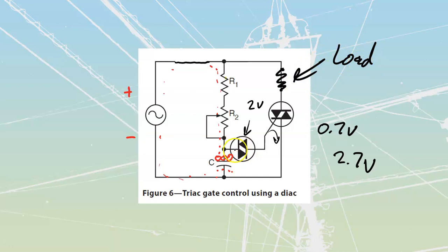All right. Over here, we see that these two are going to be in line, and they act as if they are two switches. Once we reach the proper value of voltage for both of these, both switches are going to close. This 0.7 is going to be met. This 2 is going to be met. And we are now going to run current through there. What current is going to run through there? Well, if I take a look at it, I'm going to run off this current through there. Those electrons are going to leave from here because they can travel through here. They're going to travel through here, back through this. Remember, it can take current through in either direction to drop the value of voltage that's across there.